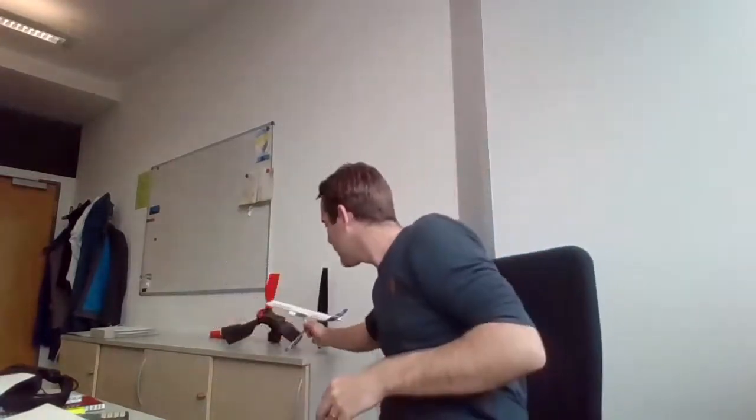So where the wing can shake, you have like resonance frequency. There, a pure PID controller will probably not work. You can add something to cancel, for example, that, or to shift it. You can do all that with this method, but for now we're sticking to the root locus method only for PID controller, but it's a very general method, so to say, for control design.